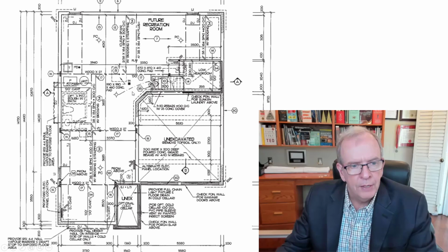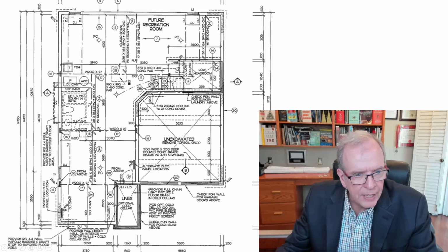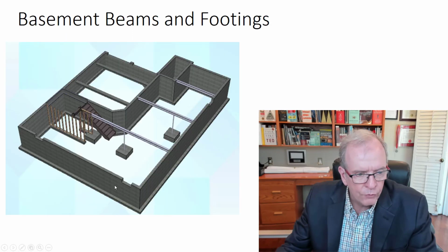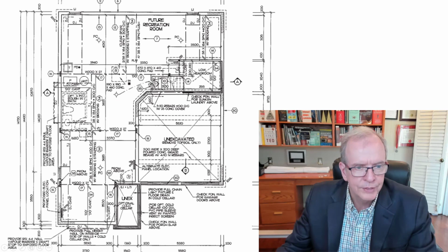And so there is your steel beams again that I'm referring to. Here is your length of wall. Here, there's that footing that would be underneath to carry that support of that wide flange I-beam. Here's the other steel beam, and here's the other steel beam over here. So again, you got that steel beam, this steel beam, that steel beam going across. You got this footing, that footing, that footing, and then this strip footing for that particular wall to sit on. So you're starting to get the idea of what's going on here.